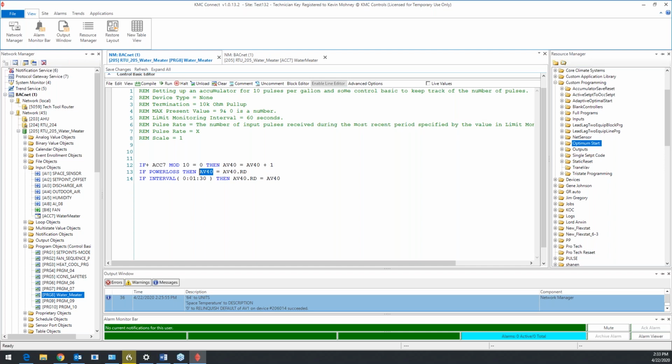However, if you had a site that was at 35 or so BACnet devices and it had been deployed for a while and they're adding more to the building or adding a new building and adding 50 or 100 more BACnet devices, and it's already licensed on that site key for TC BAC, you can then just purchase TC BAC Unlimited. You do not need to purchase TC BAC again. TC BAC Unlimited is an upgrade to TC BAC, so you can just purchase the TC BAC Unlimited at the time, if you have a site key that already has TC BAC on it.